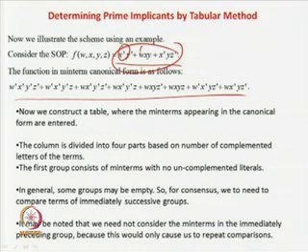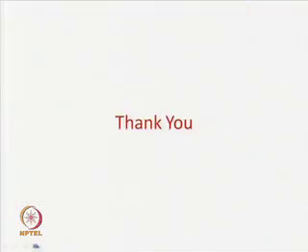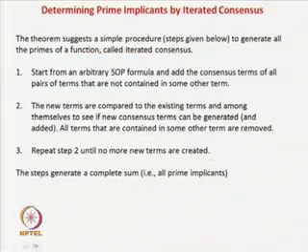We will have consensus between these two terms, and again between these two terms, and again between these two terms, and at every step we generate some new terms. Whenever we generate new terms, we have to check whether any terms already involved are totally incorporated in some of the other terms, and those have to be eliminated. Then we repeat it again and again. That is, we again go for iterated consensus with the new term added, and then again find out if anything is included, and we keep on doing it till we find a case where no more new terms are generated. Then this procedure will give you the set of prime implicants.